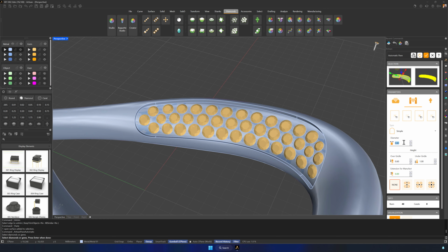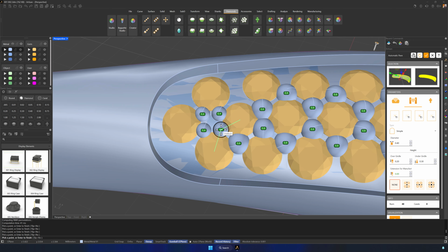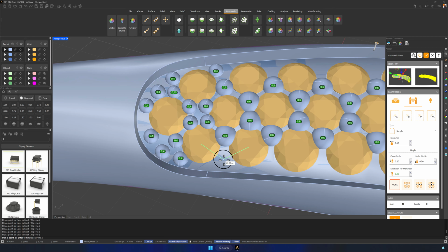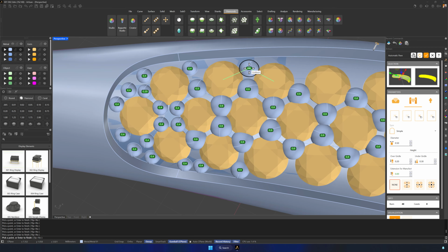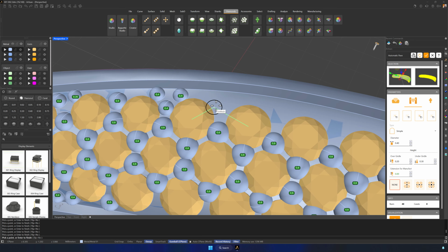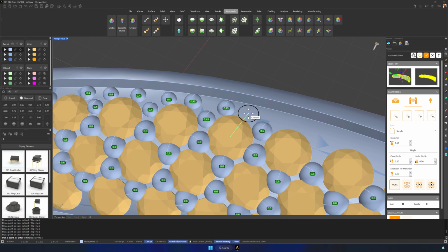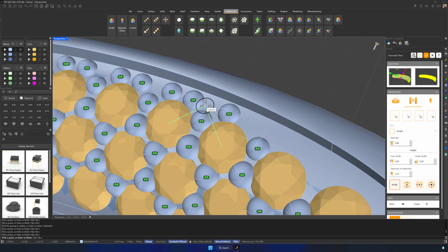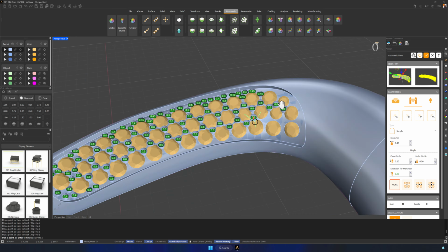Set the diameter to 0.6, the overgirdle to 0.2 millimeters, and the undergirdle to 0.3 millimeters. Then click Compute automatically. After that, add the remaining prongs manually. You can adjust their sizes and finalize the model according to your own style. Every designer finishes pave settings differently, so this is the moment to be creative and personalize the design.